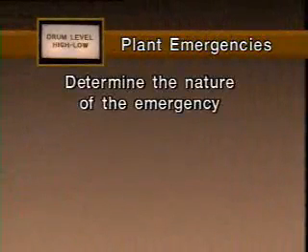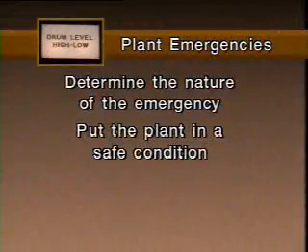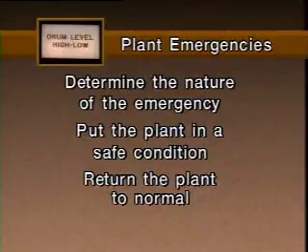Let's examine the general actions that should be taken during any plant operation emergency. Basically, there are three actions. First, determine the nature of the emergency condition. Second, put the plant in a safe condition. And third, return the plant to normal.